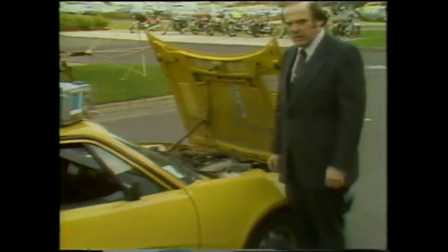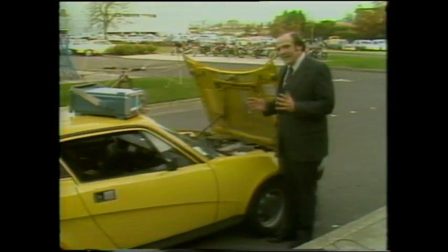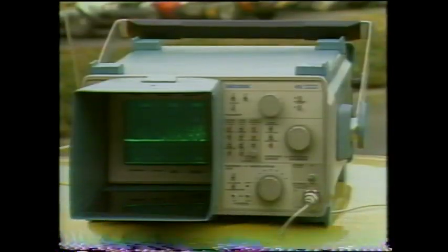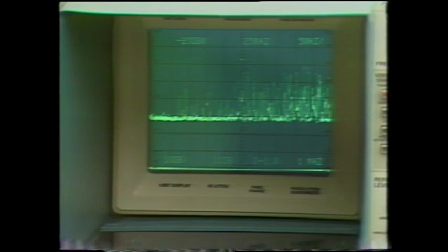Making measurements of impulse noise is also easy using a spectrum analyzer. Man-made noise like that from an automobile engine is called impulse noise. To measure it, you have to determine the impulse bandwidth by using one of several methods and then normalize to the correct bandwidth, just as we did when we measured random noise. But note that impulse noise is expressed in volts per bandwidth, and because EMI is a broadband measurement, most impulse noise bandwidths are normalized to 1 megahertz.